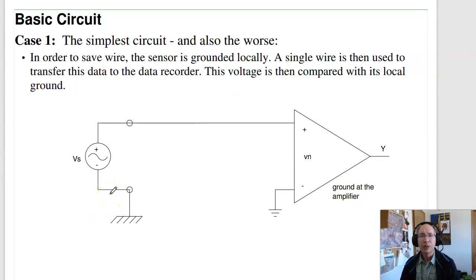One approach, the approach that's actually the worst, is if the smokestack I've got to ground, at the amplifier I've got to ground the 2 points. That's bad. This is kind of like Cincinnati and Columbus. I ground Cincinnati, ground Columbus. What's going to happen is these are different voltages that produces current.